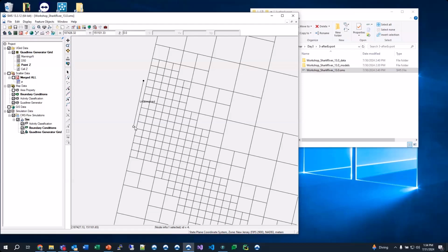If it's wide open, it shouldn't be a problem, but there may be some cases where you need that. So it's just a matter of, if you get instabilities, play around with it. That's my recommendation. When we implement this, I always look at what the angle of the normal channel is, and I just always put it in there, just to avoid problems from the get-go.